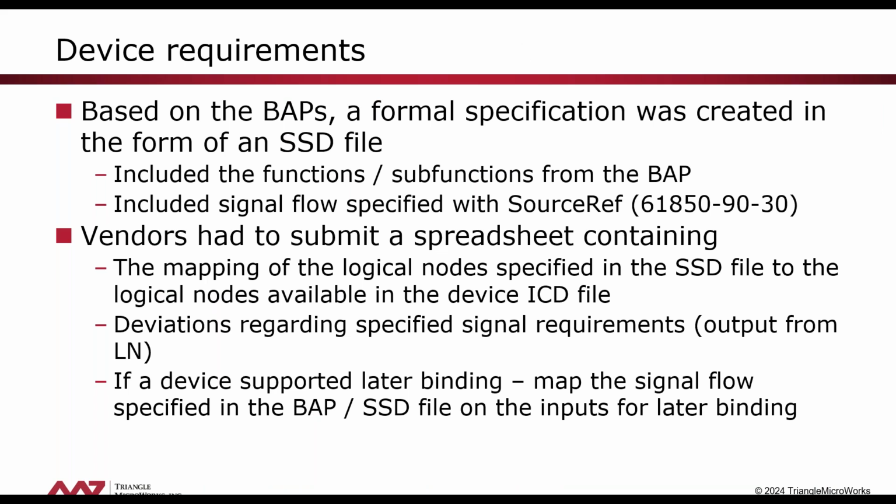So based on these BAPs, we created beforehand a formal specification in the form of an SSD file based on the system configuration language. In that SSD file, we included the functions and sub-functions from the BAP. We also included single flow specified with source ref based on this technical report that is about to be published. In order to tell us how the device implemented this function, they had to submit a spreadsheet in our process where they had to tell us how the logical nodes that were specified here mapped to the logical nodes available in the ICD file.